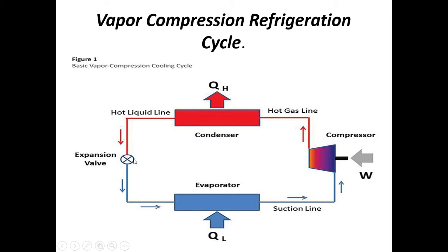So that means when a liquid refrigerant at higher pressure passes through the expansion valve, it flashes. Flashing means it vaporizes. A part of the liquid refrigerant vaporizes by taking its latent heat from the remaining liquid. So the remaining liquid will be at a lower temperature. Now that remaining liquid, which is at a very low temperature, passes through the evaporator coil.